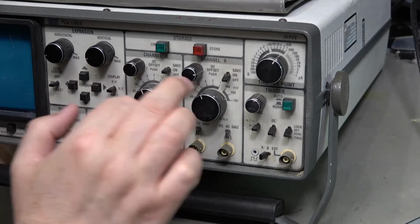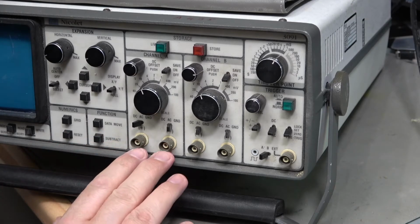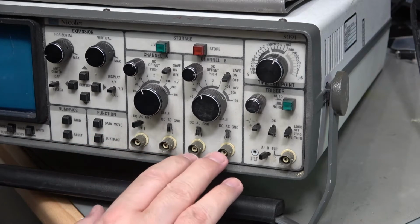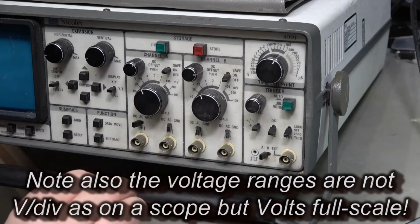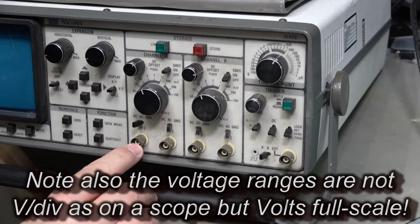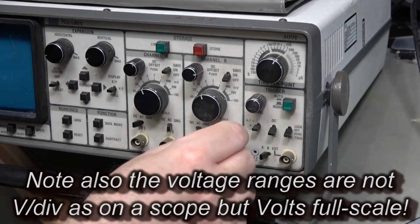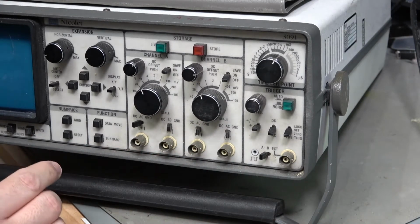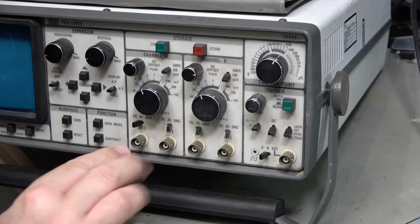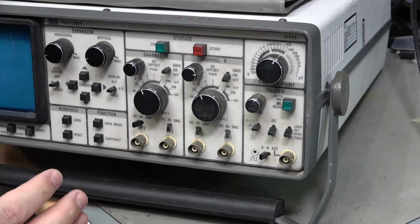And then we've got 2 channels, channel A, channel B, but they are differential channels. These are differential input signals, not single input signals. So there's 4 BNCs for 2 channels. If you want to use it in single-ended mode, you just ground one of the sides of the differential. So this is the plus side, this is the minus side. Your differential signal goes on there. So overall, an interesting piece of kit. It would be really nice to see this up and running.